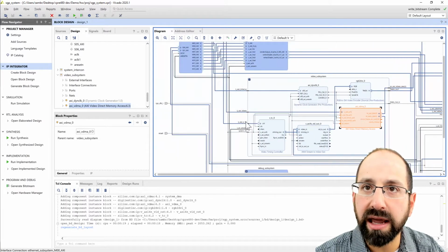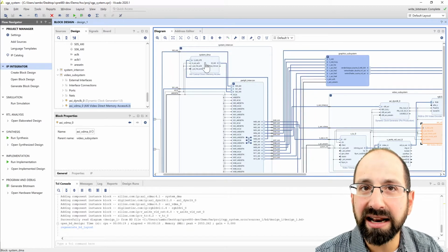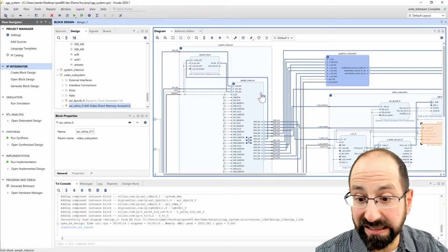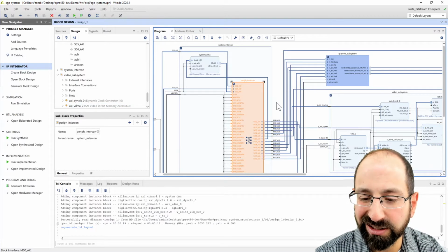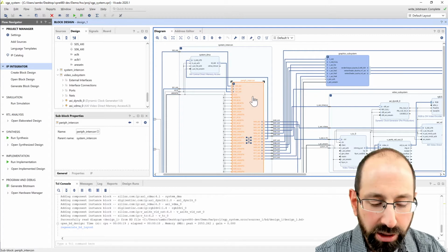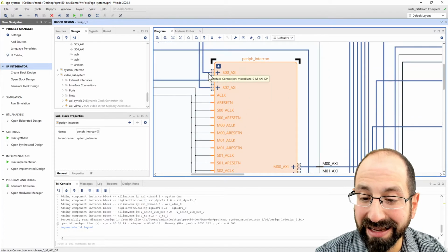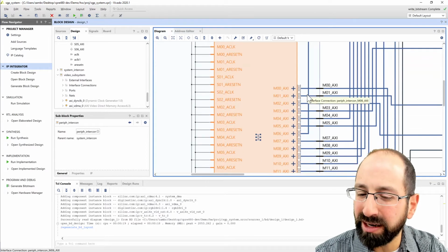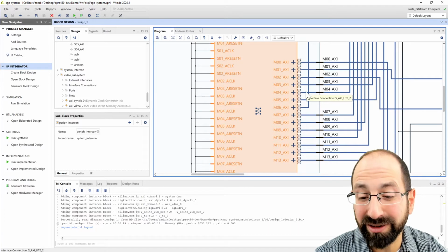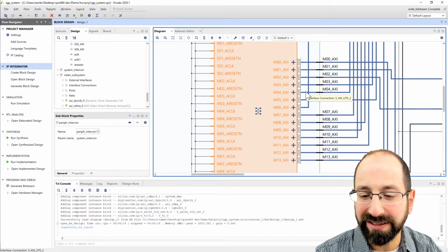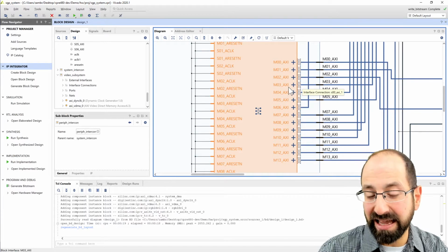Separately in this system we have here, we already looked at this briefly in what I labeled as the system interconnect. There's not a lot in that other than a DMA block, a separate DMA block for just doing block transfers. And now we have a much wider looking switch here that's handling arbitration. There are 3 bus masters that are wanting to access. And this is more than in your MP1 design, but you'll keep adding to this, a whole bunch of, in this case, 14 different IP cores we're connecting to the bus here. Anything that we want to configure over the AXI, that's the path that it's taking.